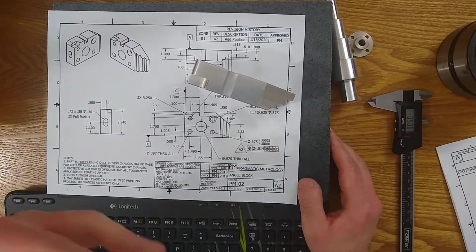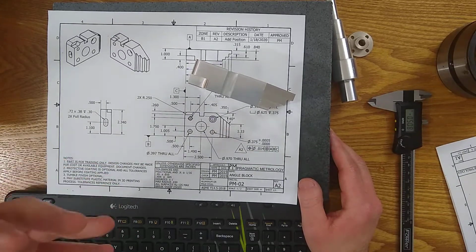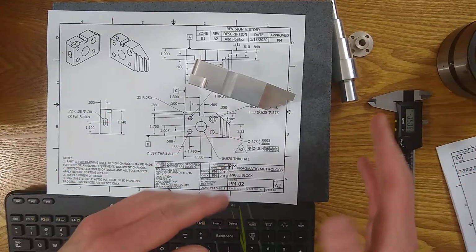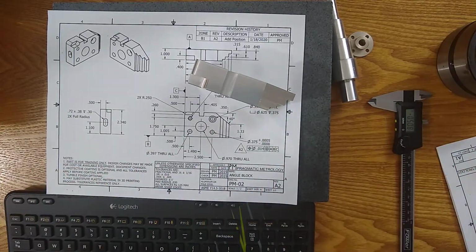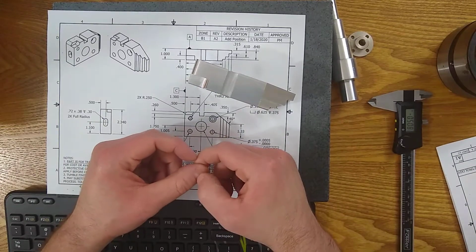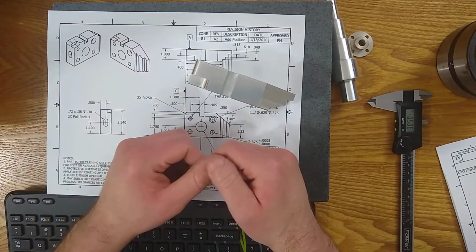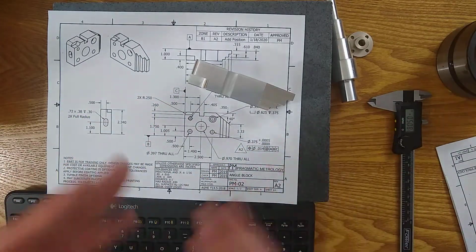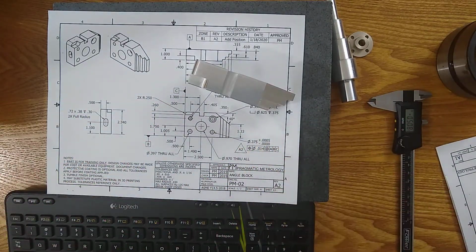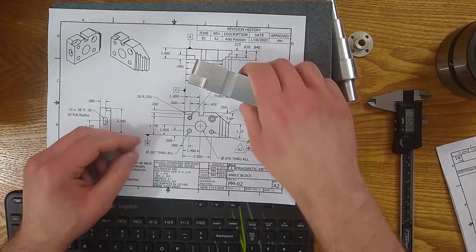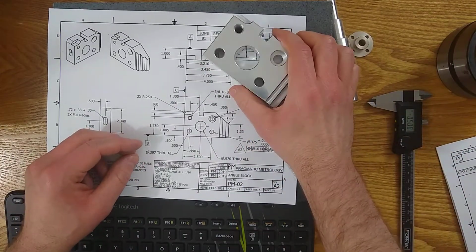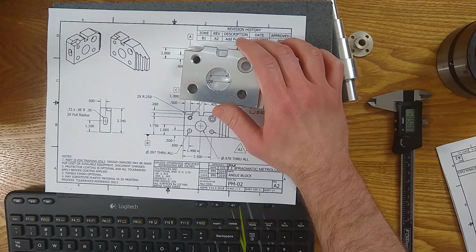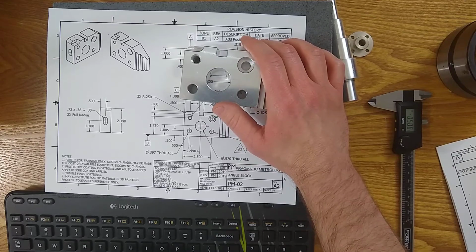So if you have to cheat, you want to cheat a little bit deeper without poking through, without affecting any other features. If you can do that without affecting any other features, most of the time people won't care. And again, you should probably get the print cleared up. If you're going to have to go deep, just get it cleared up. It's a simple change, and it'll make everything more efficient. So if this were a real print, I would change it. But it's just an example.